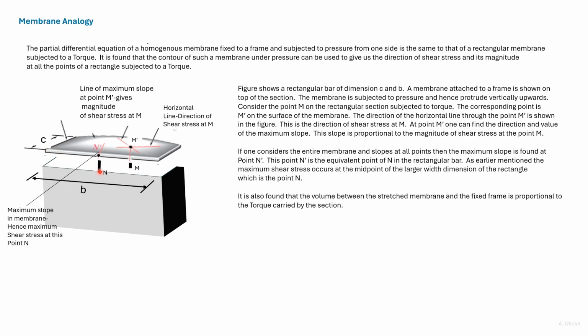Let us consider that there's a pressure acting on this homogeneous membrane that gets the membrane bloated as shown. The partial differential equation that governs the behavior of this membrane is the same as the partial differential equation of a rectangular section subjected to a torque.